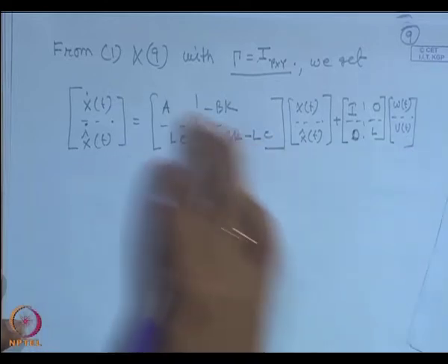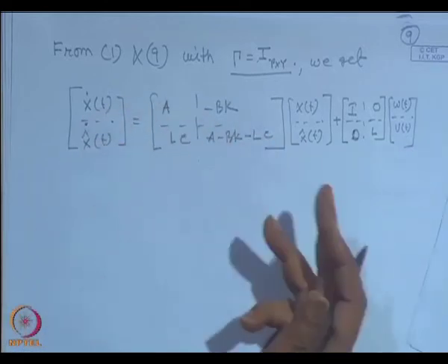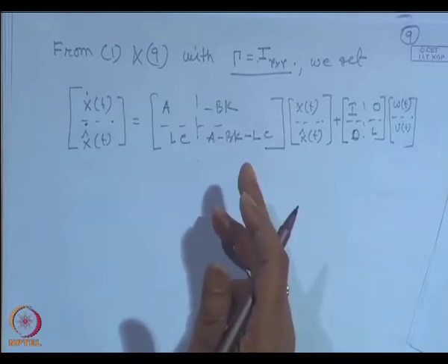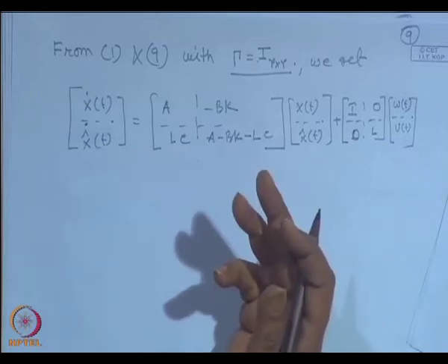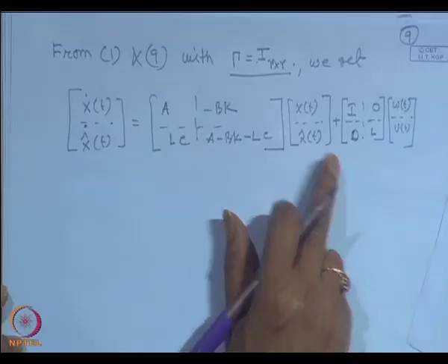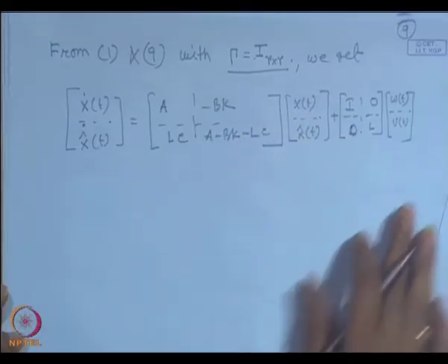But from this we cannot come to a conclusion whether the estimator design, Kalman filter design, and the controller design can be done independently or not. That means, whether the separation principle is applicable, we cannot say.